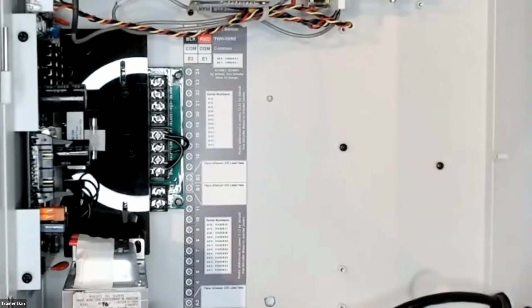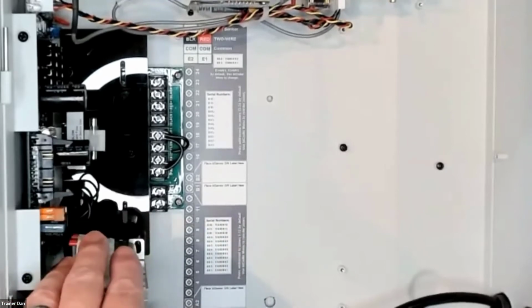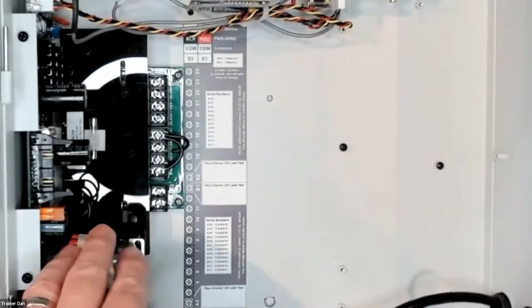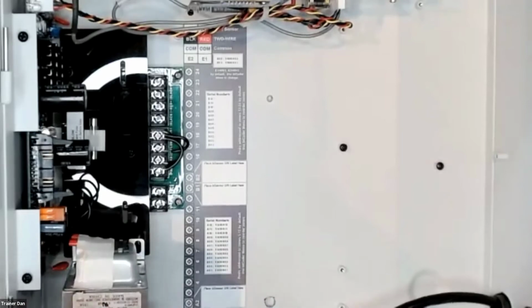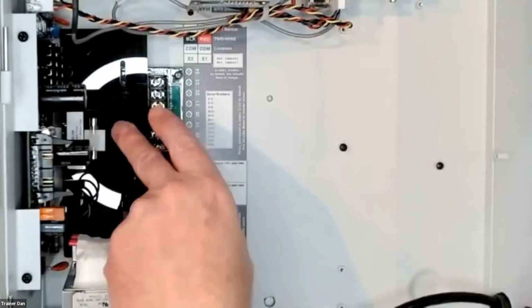So I could check high voltage and I could check the output voltage of the transformer. So that's an excellent thing to check on the controller: power in and power out of the transformer. Do we have it, or do we not? There are some fuses on the board.